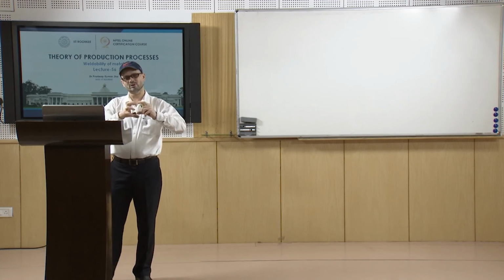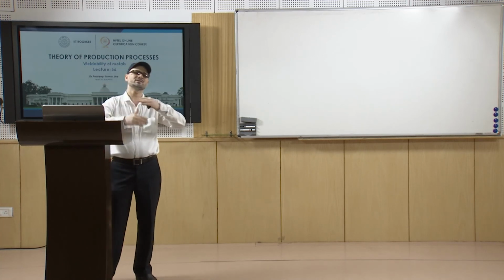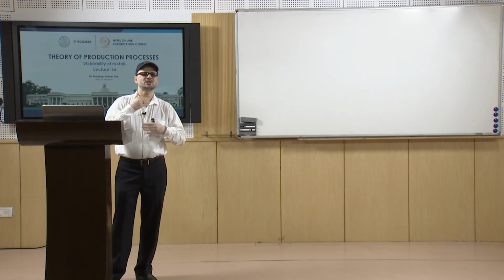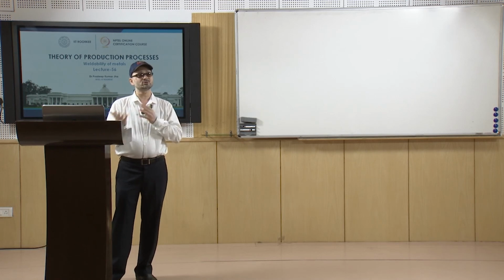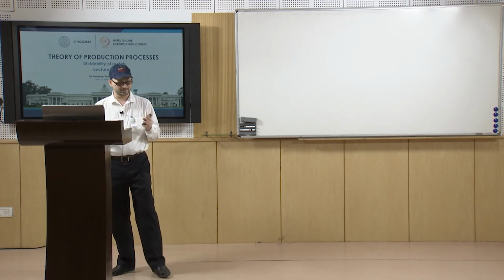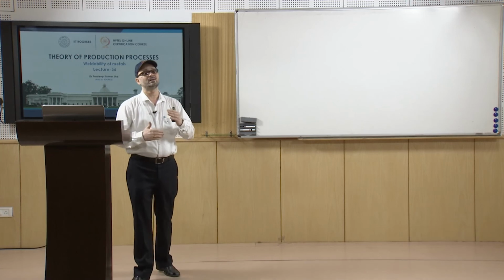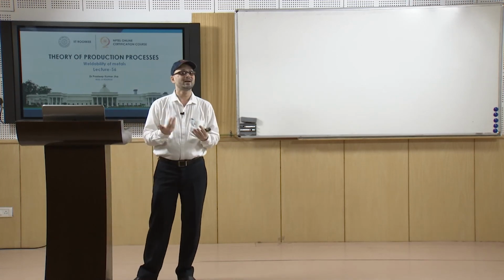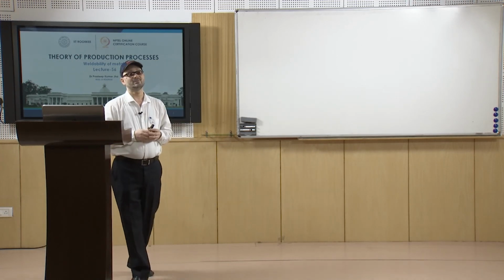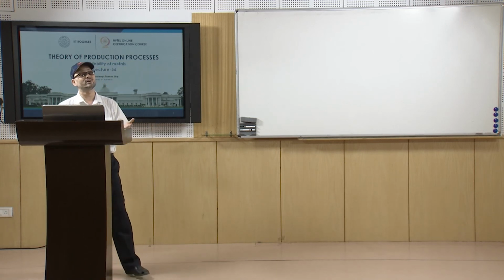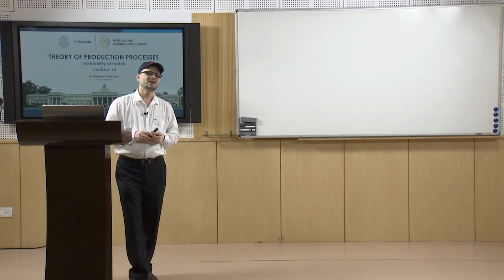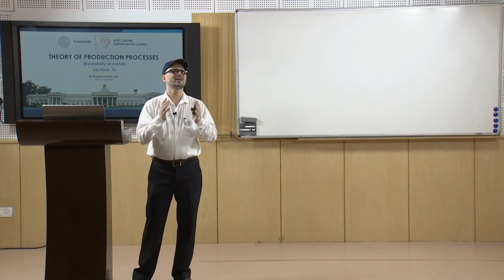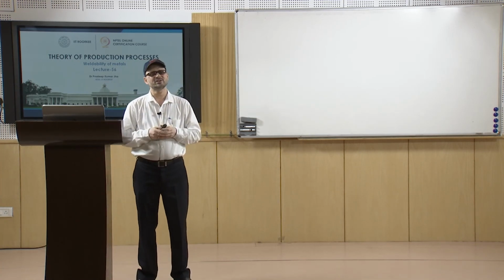So, once you have done the welding, you see how much it has affected the tensile properties or the hardness or impact properties or corrosion or fatigue. This way also you can test the weldability. If it is not affected, it means the weldability is better, and if it is affected, it means the weldability is poor in that aspect. So, this way you have different aspects based on which you can check the weldability of the material.